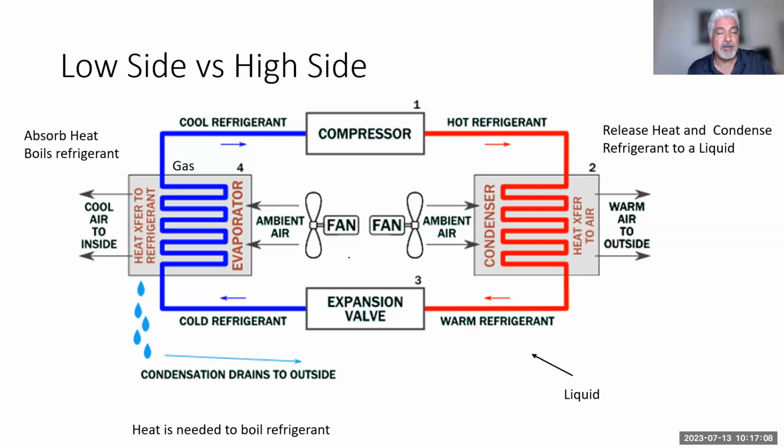I don't need to tell you, by the way, before I forget, in servicing a 134a system with PAG oil, you all know that PAG oil is hygroscopic, correct? So a lot of us use mineral oil on the O-ring. Do not put PAG oil on the O-ring seals, because that is hygroscopic. It absorbs moisture, so it will attract moisture. That's why in some very humid areas we have seen growth or mildew around fittings. That tells me somebody put PAG oil around the O-ring. So you do not use PAG oil on O-rings to lubricate them. You use what? Mineral oil. And you can still buy it at your local auto parts store. So keep that in mind.